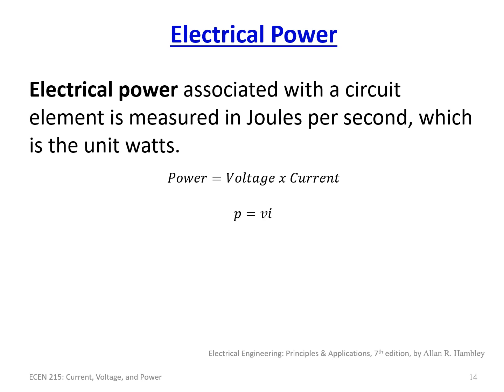So what we end up with is simply P is equal to V times I. And of course, this could have a time component. So voltage is going to vary with time, and current could vary with time. So this could be V of t times I of t, which gives us power of t at a specific time. And of course, the formula is joules per coulomb times coulombs per second. The coulombs cancel out, and you end up with joules per second, which gives us the unit watts.